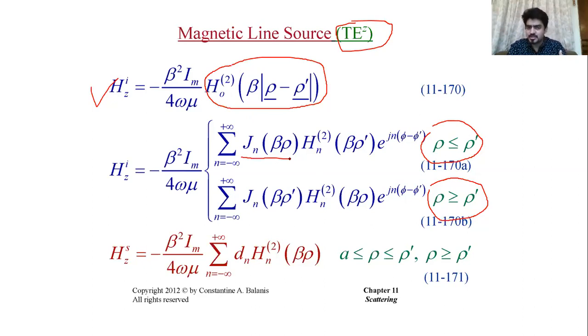So with respect to rho, here you will see a Bessel function of the first kind. Why don't we use the second kind? Because it has a singularity at the origin. We want to avoid that kind of singularity in our field distribution, and that's why we get rid of the Bessel function of the second kind. So we impose that additional boundary condition.